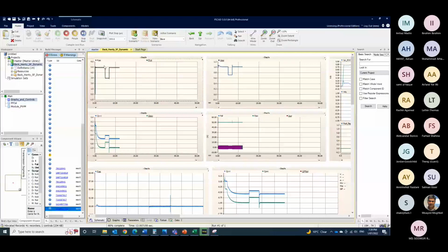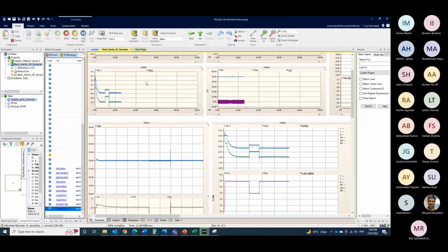So as you can see, there is the power dip and similarly the voltage dip when there was a fault, and the inverter system managed to ride through the fault instead of shutting down. That's from the reactive power.